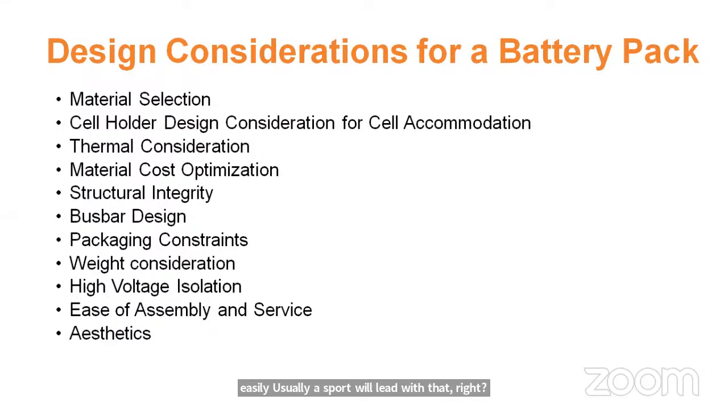If you are going for the laser welding application, then in laser welding, what will be happening? These similar materials also could get welded. But you have to be very cautious about the diffusion in laser welding. The top of the material, the bus bar, gets melted, it gets diffused and goes inside the cell terminal. So this material should easily get diffused. Those are all parameters you have to think about when you are selecting the material for the bus bar.